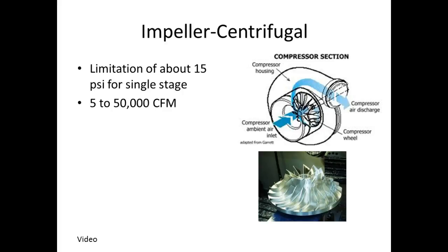Impellers. These are impeller or centrifugal compressors. Basically, it comes in here and pulls air in, and then it narrows when it comes out, and then it shoots out the center. Then they cool it down, and they'll run it into multiple stages. Most of your centrifugal compressors are definitely multiple stages, maybe up to seven stages that this thing will go through. And each stage, they get closer together, right? You understand? So these are centrifugal compressors.